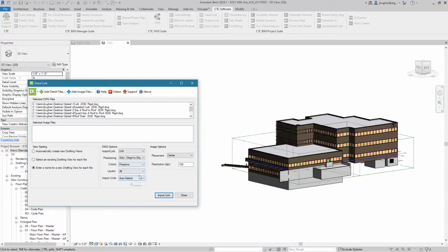A lot of you guys know exactly what you would choose here for DWG options, but I'll pretend like this is a Revit fundamentals class for just a minute here and kind of explain my approach to making choices with importing here. We do have the option to either link or import. And if you guys have been using Revit for more than 5 minutes, in your minds, you're probably thinking, well, it shouldn't even be a choice. It should just be link, because that is undisputedly best practice. However, there are times that you do need to import in DWGs. It is the exception rather than the rule.